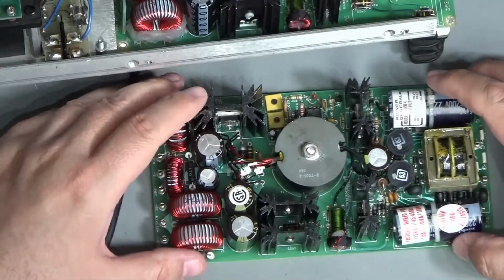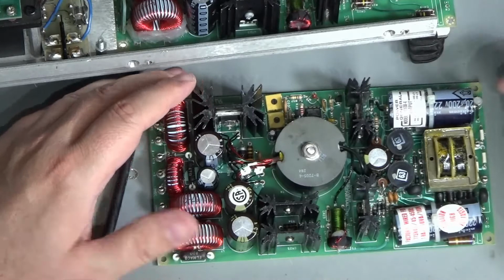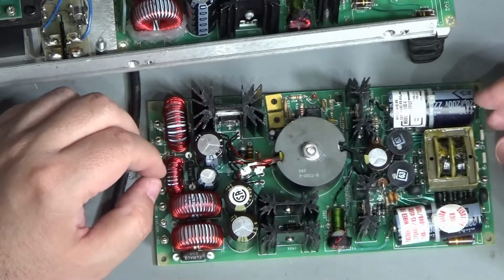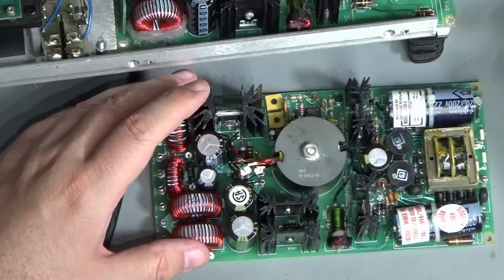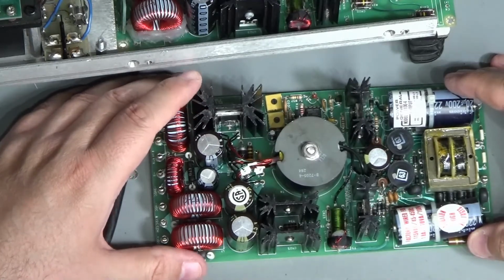So I'm going to connect this. When I connect this to the mains, I'm going to wind it up quite slowly. I'll put a variable voltage on the input and just wind it up slowly from about 50 volts until we reach 240.